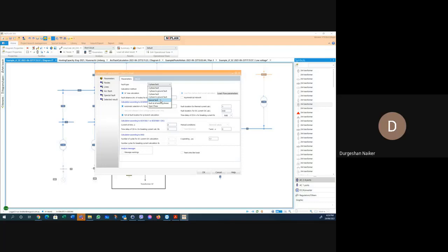It means you could have a 132 kV line running on the same pole, a shared pole, with, let's say, an 11 kV line. What if that falls onto the 11 kV? What will happen? Neplan can also study those sort of things from one voltage level to another voltage level, not only to ground or within itself. So it's quite an amazing tool. There are various things it can do, so I will just do a 3-phase study.